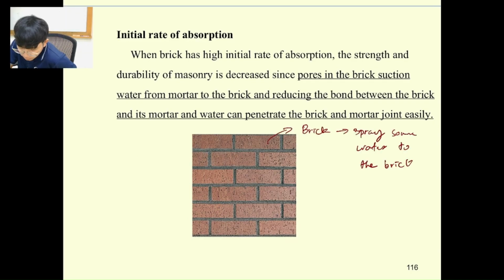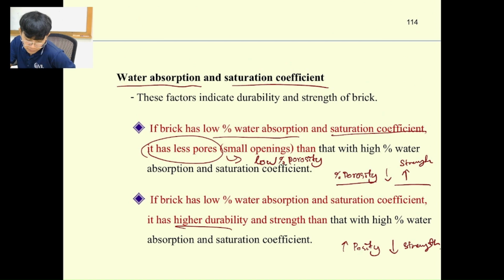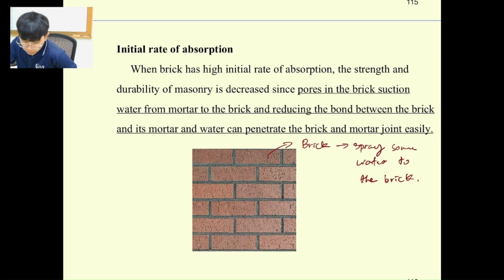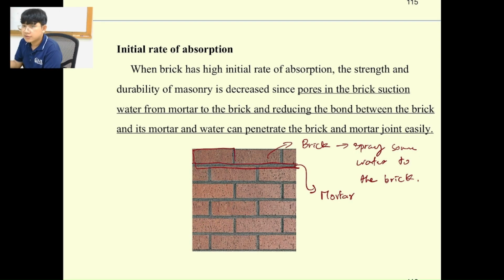Because in brick, as you may know, we have water absorption. If you mix the mortar and place it here, and after that you place the brick on top of the mortar, the brick is going to absorb the water from the mortar, and sometimes it can cause cracks in the mortar, or it may not bond as you expected from your design.